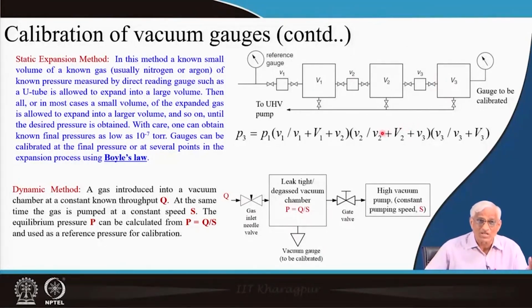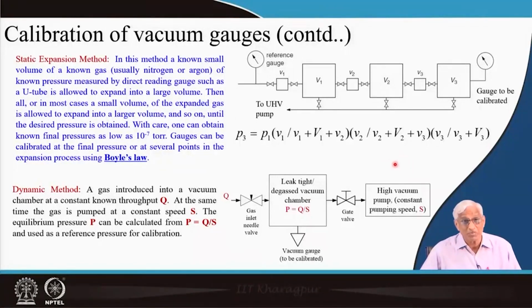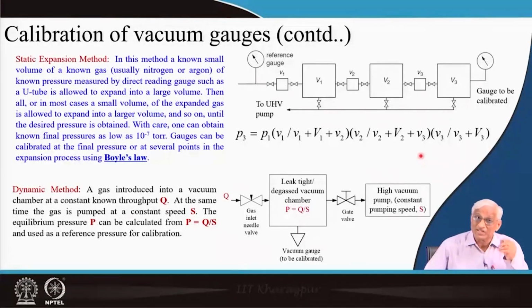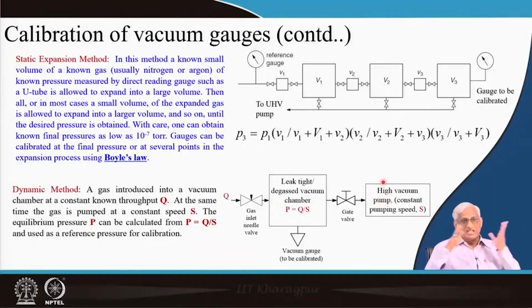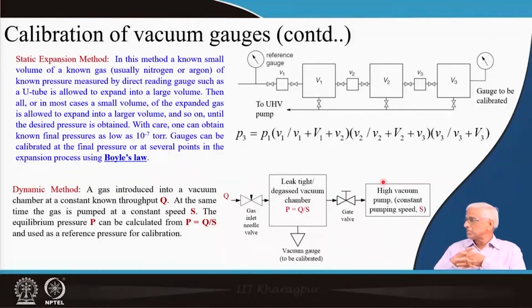Optical intensity is also there, all these standards have to be maintained, then only they have meaning, then only it is called physical measurement, otherwise it is only measurement, erroneous measurement, and errors have to be minimized. The moment you have secondary things, the calibrations have to be done, and they should be reliable calibrations. So, this way we have to take care of this. Measurement we have covered: various gauges, thermal conductivity gauges, ionization gauges, static expansion methods, calibration procedures, and care of the gauge, how to clean these things and all, that we will see in the system design.